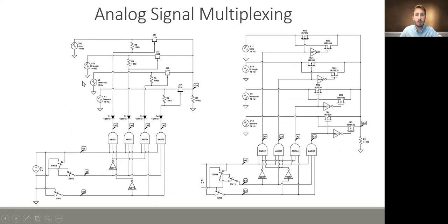So this here is our JFET or FET multiplexer. What we're going to do here is we've got 2 select lines. So this is a four line multiplexer, and this line here is simply an enable line. But we've got our 5-volt logic source here. And these switches here I had to do in CircuitLab to get a transition in the select line. I'll show you the simulation results here in a second. But this basically just switches through a combination of our outputs. So it'll select the sine signal first, then triangle, and sawtooth, and square.